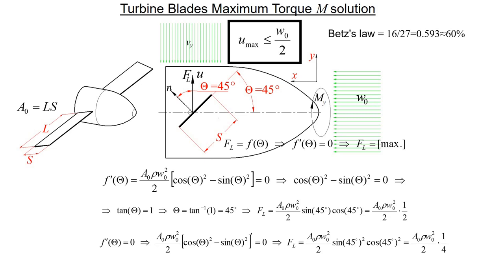The maximum pump flow rate is known from the pump specification by the pump manufacturer, and in the design pipeline we calculate total loss of pressure over flow rate. In this instance, pump impeller geometry is not important. However, for open windmills or aeroplanes, geometry and surface area of the wing or blade are essential parameters.